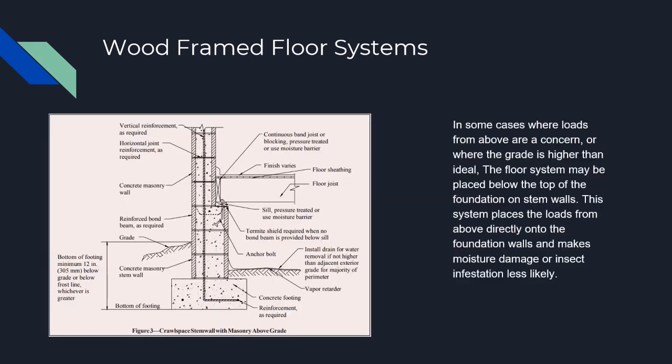In some cases where loads from above are a concern, or where the grade is higher than ideal, the floor system may be placed below the top of the foundation on stem walls. This system places the loads from above directly on the foundation walls and makes moisture damage or insect infestation less likely.